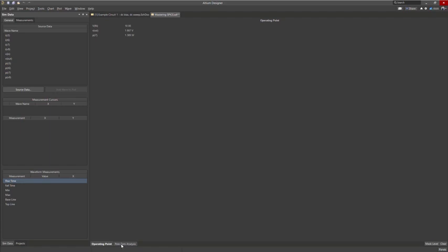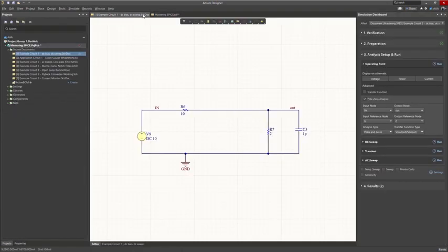And at the bottom, we'll click on the Pole Zero Analysis tab. And if we click on Pole, at the bottom here, it'll show me where my pole is at. This does not have an imaginary number in this expression. This pole is all real. And if we highlight, we can see where that is. Also, it's down here. And if you want, you could even zoom in, but really the value is what we're looking for. So this can really help you understand your circuit and its stability.